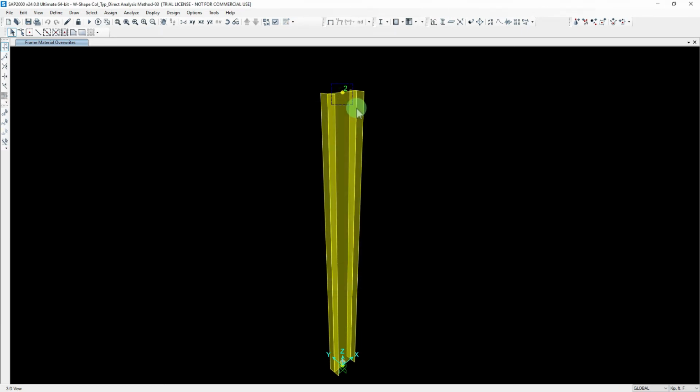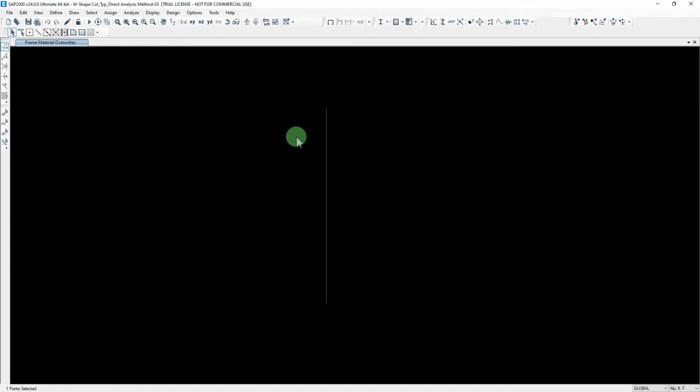So apply some loads. For my vertical direction, I will apply a load of 32.7 kips in the vertical direction, going down. Why 32.7? Because I've actually calibrated the structure to fail at that load.